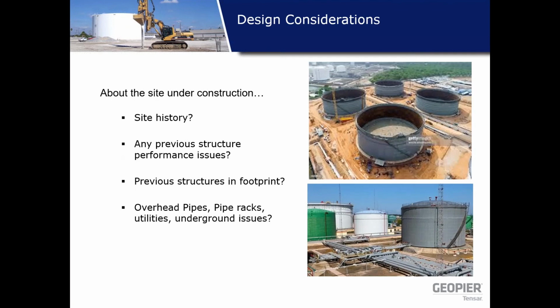What happens in the field? Site history. As you know, a good site is hard to find, and we need to know where these tanks will be constructed. What was that site? Was it a dredge fill site? Was there any previous structures present on this site?